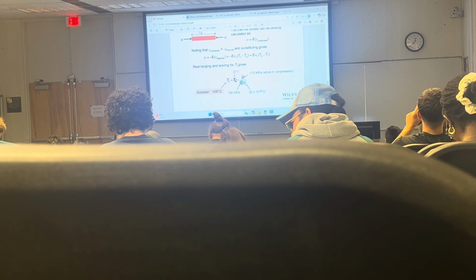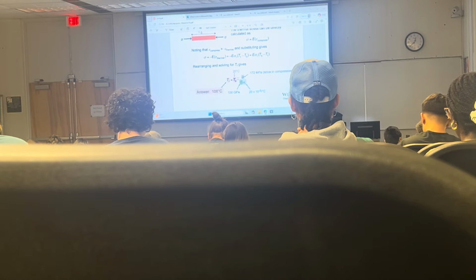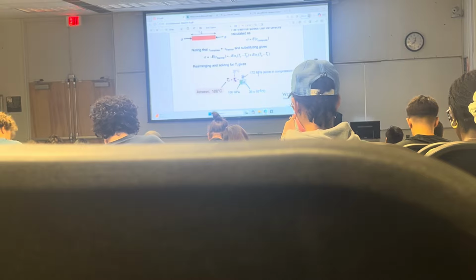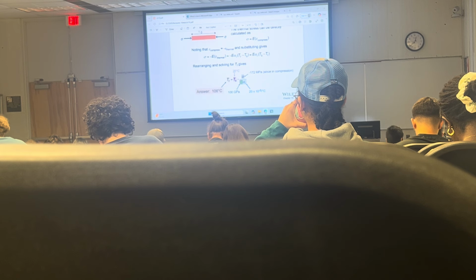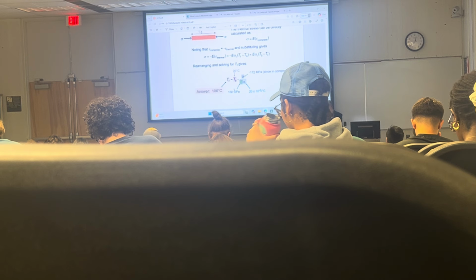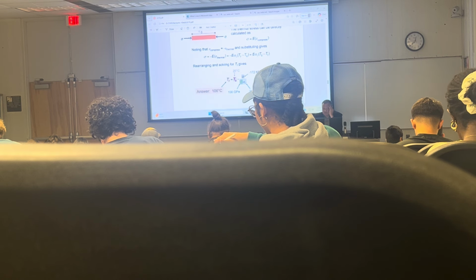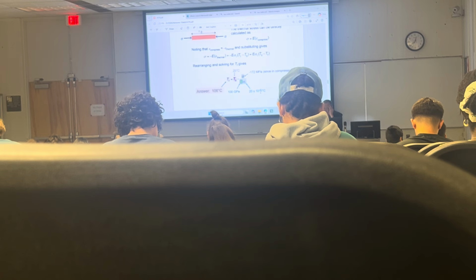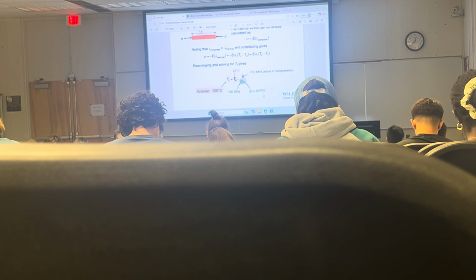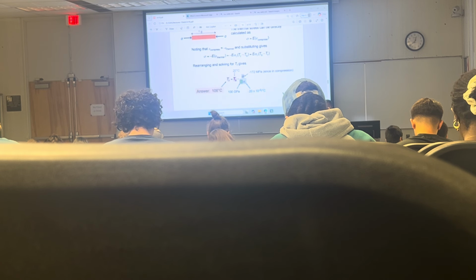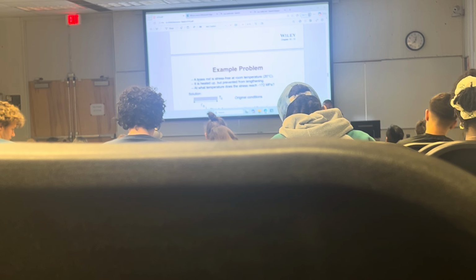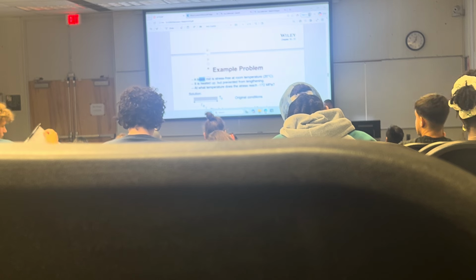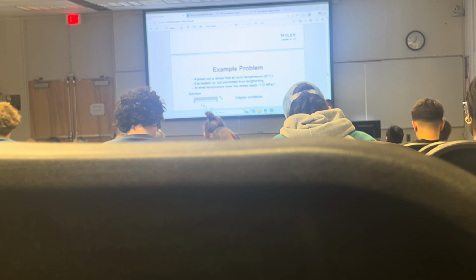So we get T0, which is room temperature, 28 degrees centigrade, plus minus sigma, which is minus 172 megapascals because it is in compression. That's what's given in the problem, divided by the elastic modulus, which is 100 gigapascals, divided by the thermal expansion coefficient, which is 20 times 10 to the minus 6, 1 over degree, the thermal expansion coefficient of brass. And you can look it up in a properties table.